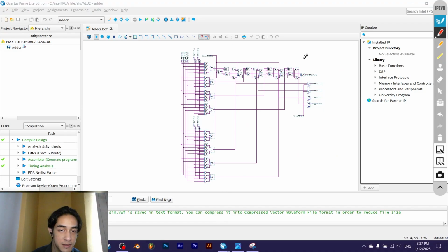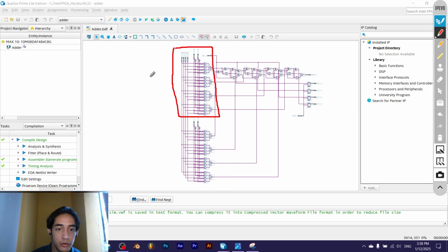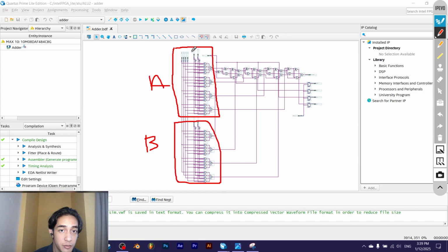So over here we can see the final circuit diagram for ALU operation. On the left side over here we have the multiplexers. One is for A input and also the bottom one is for B input. Each of the multiplexer will have their own selector. For A it has S0 and S1. For B it has S2 and S3. So these multiplexers, we go to RCA subtractor and it will perform addition and also subtraction operation, and this register will combine the outputs from RCA subtractor and we will have the final sum.